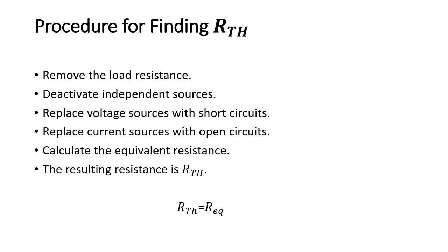I'm repeating this step. First, we have to remove the load resistance. Next, we have to remove the voltage source, that is, we have to short circuit the voltage source. And if the current source is given, we have to open circuit the current source. After doing this, we have to measure the resistance across the load terminal, which is Thevenin's resistance RTH.